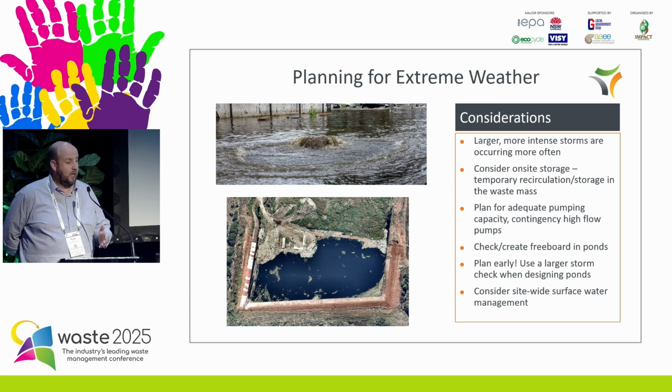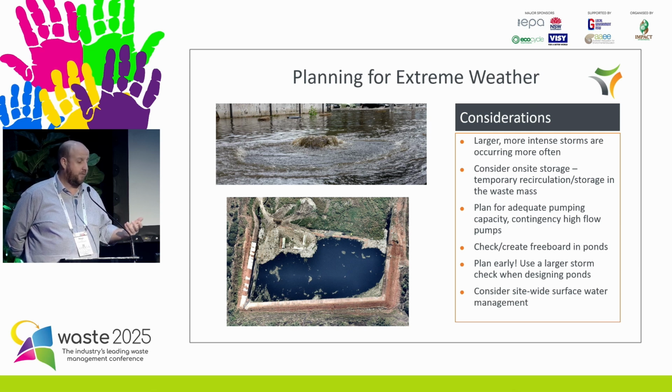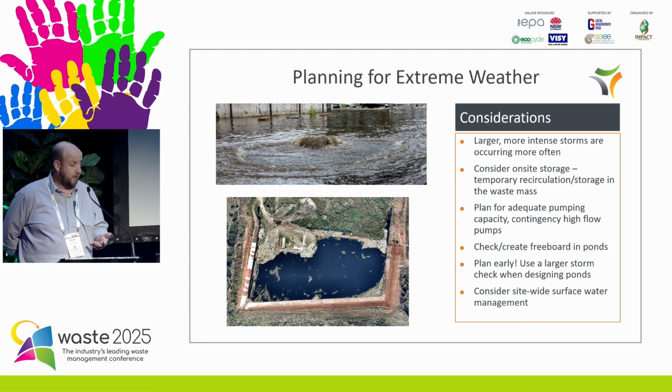So just really be taking that conservatism, but not just on the design, also in relation to contingency, as in, are the pumps even suitable or large enough to pump out that volume of water from your leachate or from your ponds and so on and so forth? Is the freeboard enough? So really just emphasising the point, when you are designing not only your leachate system, but your surface water system, which Kate touched on, that conservative approach nowadays with our changing climate is really important.